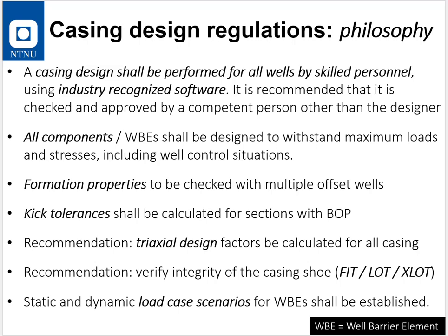Recommendation: verify the integrity of each shoe, meaning before you start drilling a full section, you need to know that the previous section is fully isolated. Doing an FIT is fine, but then you get basically not much information from the formation. You just know that yes, my shoe has the integrity enough to drill the next section. Whereas if you do a leak-off test or an extended leak-off test, you would know much more about the formation at the casing shoe.